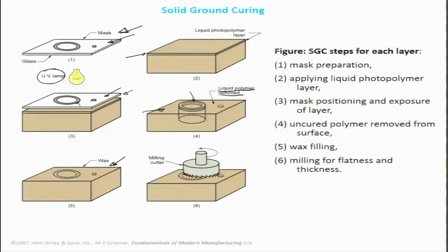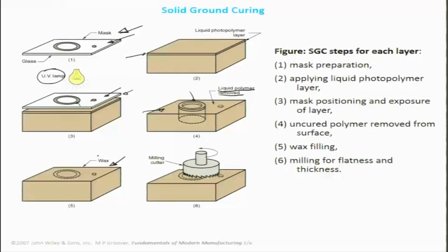Okay, so you can say that this is also sort of equivalent to the lost wax method, particularly in investment casting, where you create a feature or a shape in wax, and later on that acts as a core, and you can have metal flow over it, and you can retain the wax out so that there is a cavity which exists. In the same manner, in this particular case, we can couple this as a process between the lithography and the lost wax method.